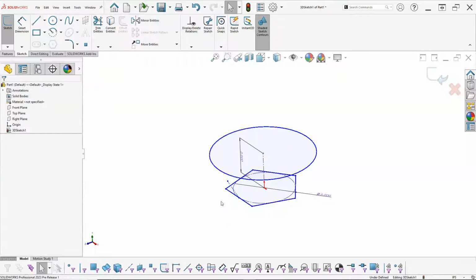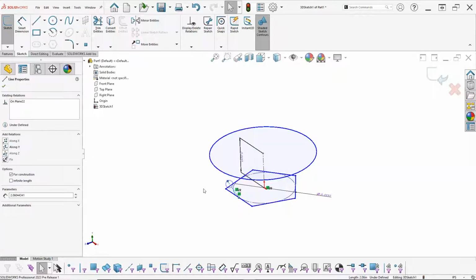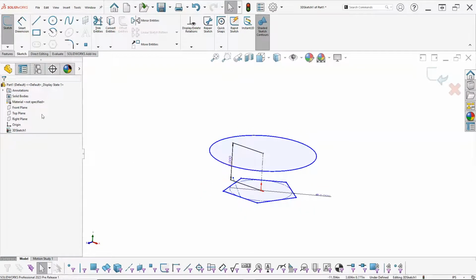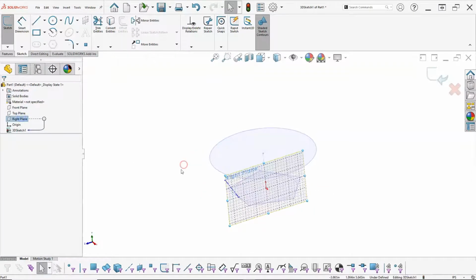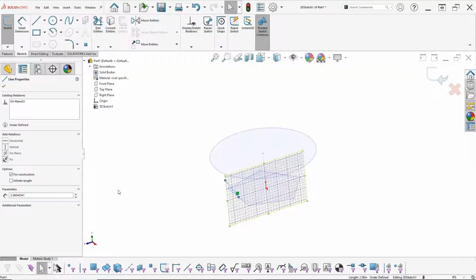Oh, it didn't activate, so I can tell it didn't activate because I don't have the grid. So one of the things we can do is, I started the line, I could have deleted it, but because that plane is active and the center line's already started, I can say put it on the plane. Otherwise it would kind of rotate. That endpoint would be coincident to the midpoint of the horizontal line, but everything else would be able to move in all directions, really an orbit.